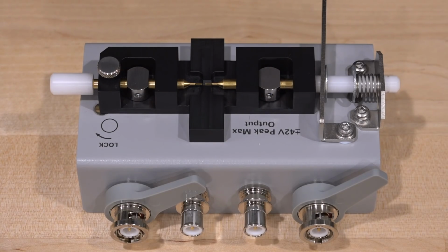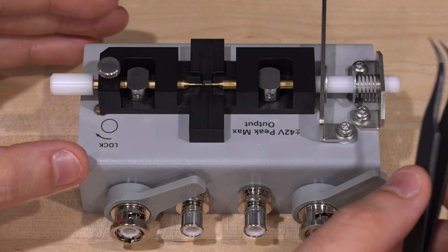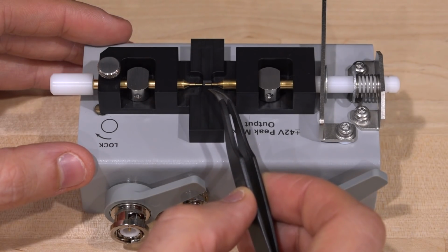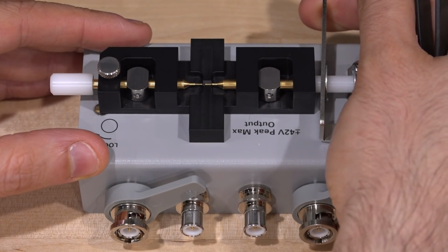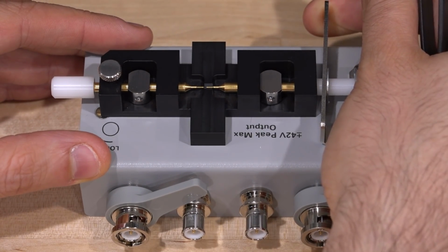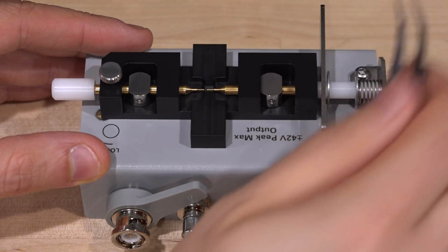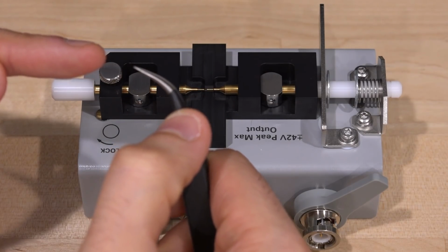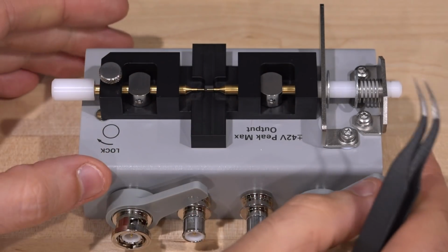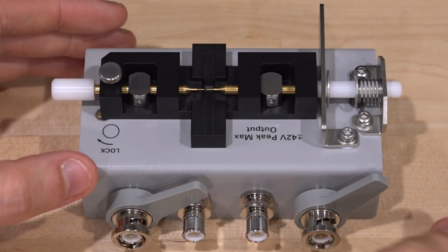Now check out this fixture. This one is really interesting because it allows you to measure tiny surface mount components with very high precision and repeatability. It's adjustable. You simply separate these two needles from each other, which are spring loaded, and you put the device that you want in the middle right there, and these two needles come in and put pressure on both sides. From there you can measure precisely the performance of that component, and you can bin them and so on and on.